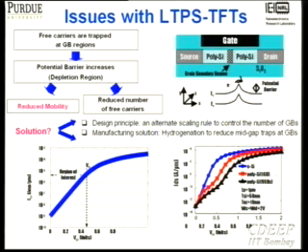I'm going to use a laser annealing process, and due to that, I can get very thin body devices, of the order of 20 to 25 nanometers TSI. If I can get that, I can make the right kind of trade-offs, body thickness optimization versus not having the best of oxide. The second thing the manufacturing solutions are looking at is hydrogenation to reduce the mid-gap trap densities.